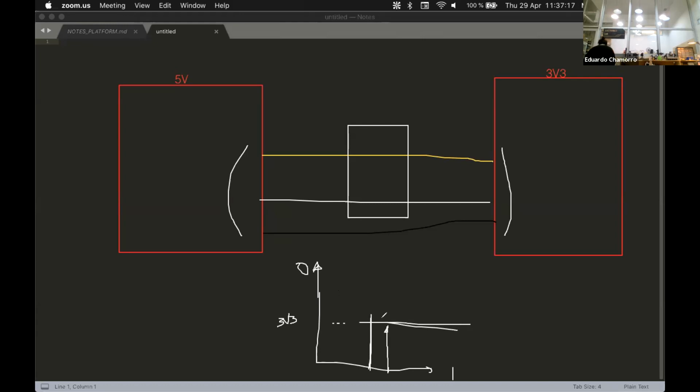So any voltage above that is going to be regulated at 3.3. Any voltage below that, well, it depends. It might do like this, or might shut down. But I have 3.3. Yeah, exactly. But it could happen, for example, let's say you have a faulty power supply and you want to regulate, if your power is 3.5 and you want 3.3. You need to really check the LDO because a lot of them have that threshold. And if you actually run below that threshold, they overheat. It's weird actually, they overheat and they burn themselves.